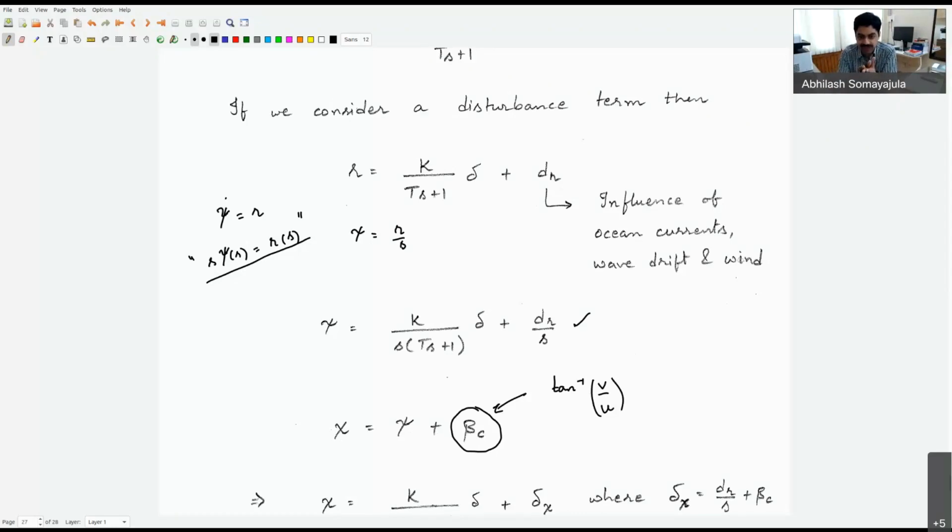The difference between the velocity vector and the heading angle is the drift angle. If the velocity is pointing in the longitudinal direction of the ship, the drift will be 0. But as long as that's not the case, you'll see a drift angle, and that is why the course angle is the heading angle plus the drift angle. Everybody with me so far?